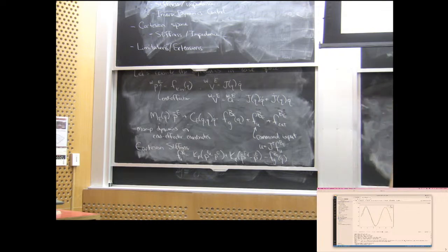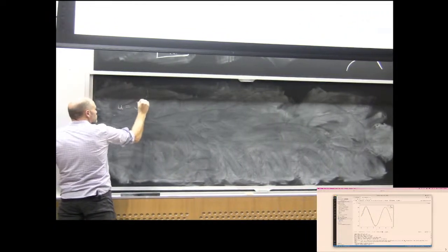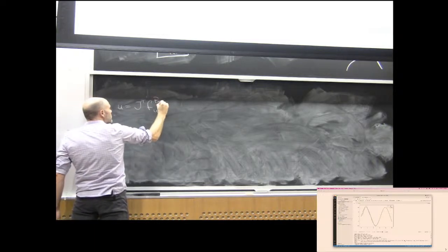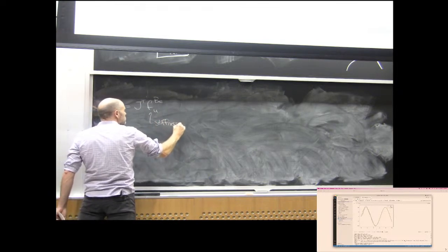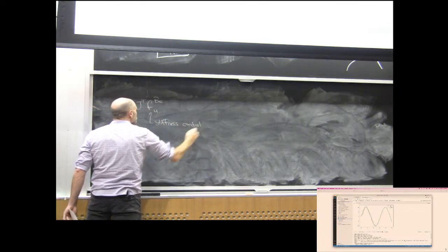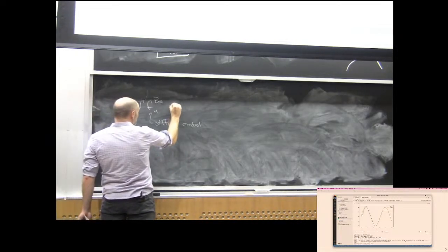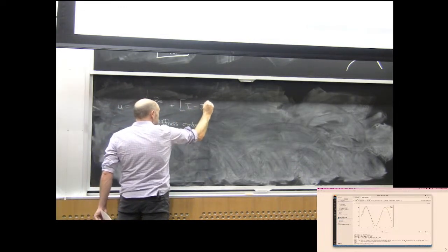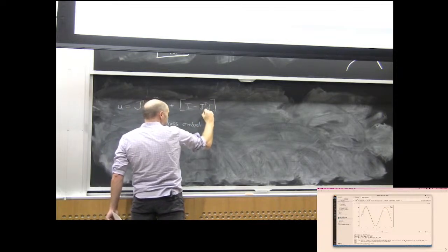How would you do joint centering to take care of that null space? If you're normally commanding this with the command that comes from stiffness control, and you want to take care of the null space, then the standard thing people would do is the null space projection.